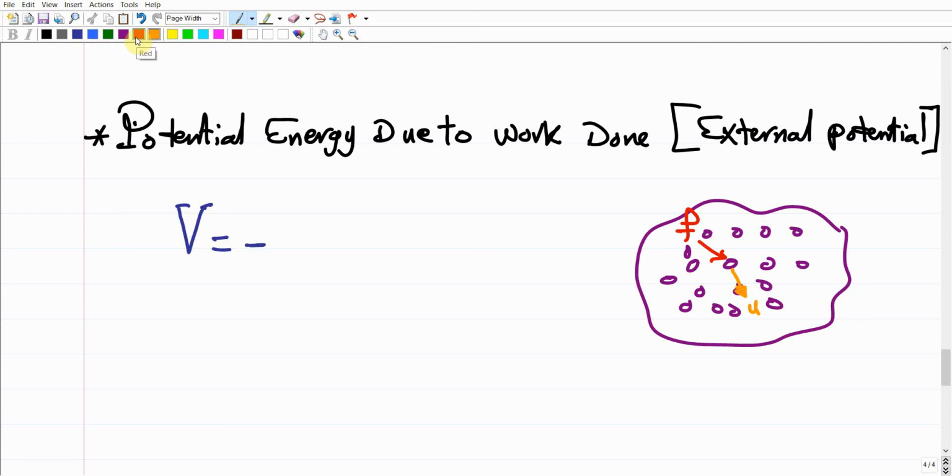But in addition to this body force, there are some other particles that are already located over the surface, right? So these are the surface particles. We said that these surface particles are already subjected to other forces, known as the surface traction. So these particles over the surface are already subjected to surface tractions like the T vector, right? All of this should be vectors in this way. Make sense? Definitely the particle located over the surface, because of this surface traction, is going to move as well with a displacement U vector in this way.